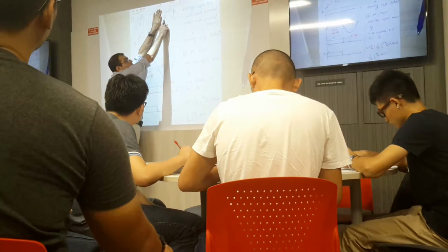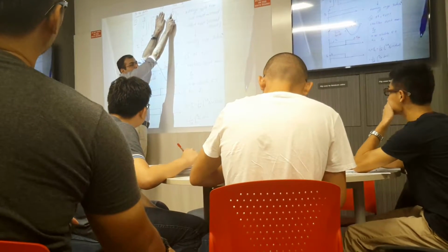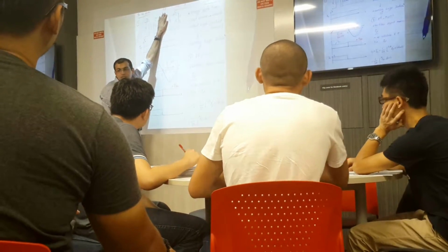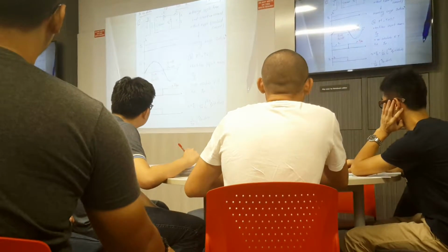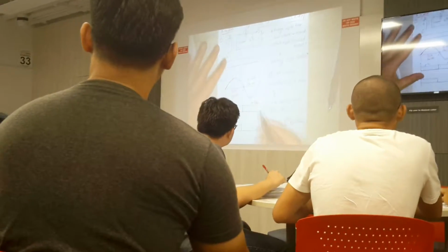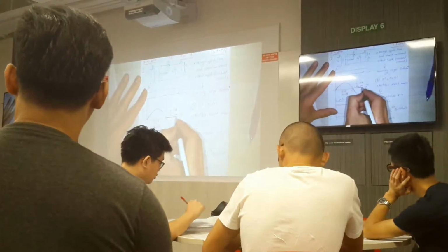So if I want to draw the output voltage again, I can see that in this condition Dm becomes on, which means that here is short circuited to this. So how much is the output voltage? It is 0, right? So if I want to draw the output voltage from pi to 2 pi, it will be 0 value.